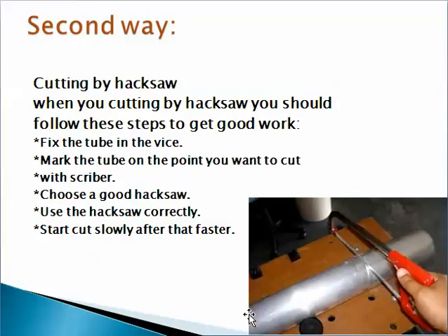I will explain the second way of cutting copper tube, by hacksaw. When you cut by hacksaw, you should follow these steps to get a good result. First, fix the tube in the vise. Second, mark the point on the copper tube.